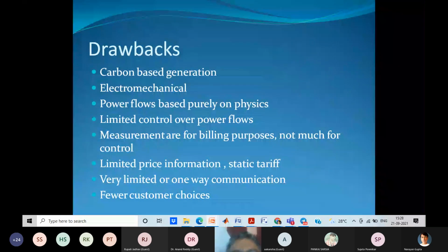You see, this question is always asked. What is phase shifting transformer? What does it do? Phase shifting transformer changes the angle and it changes the real power flow. See, P and delta are friends, Q and V are friends. That's why we use decoupled load flow. We make off diagonal terms 0 and it will be faster. And fast decoupled, we make certain more assumptions, so that the load flow is faster.